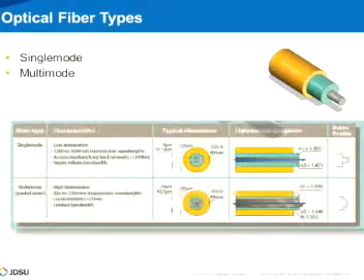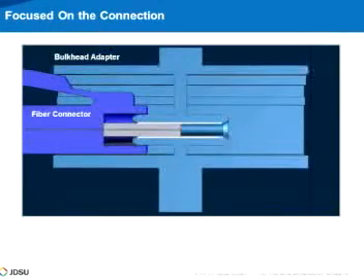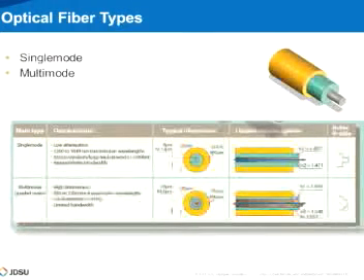the fiber that is installed depends on different configuration. Can be multi-mode and single mode. As you see here, the difference in the performance of these fiber types will determine what fiber type is used when and where. The single mode fiber is working on longer distances. Multi-mode fiber is working on a shorter distance, but it's easier to deploy due to the core size and not being sensitive to dirt. And we'll talk about it a little bit later.